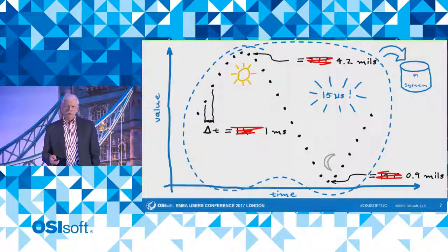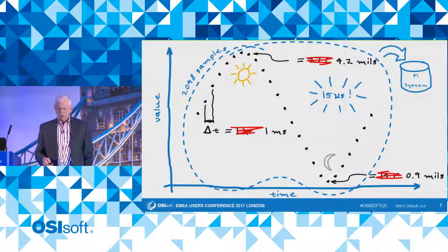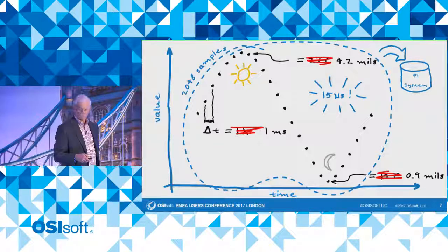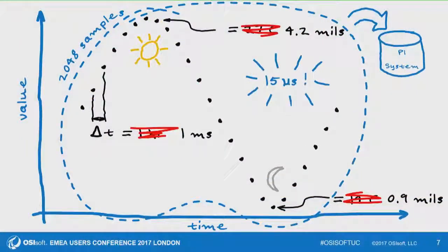So if we can timestamp the data, then we can move entire blocks of data into a PI system, which is what we've depicted here. It's no longer temperature data with an hour between the data points, it's vibration data with milliseconds between the points.